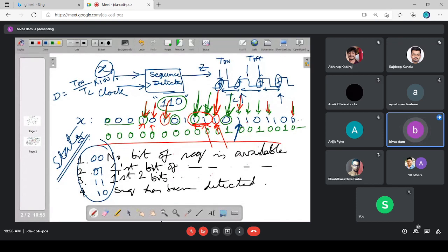Next, you have to assign state codes to those histories, and those state codes must be unique. Sir, can there be any other history apart from these four? In that case, your state assignment is not proper. You have to identify all possible histories. All means all. In this specific example, there are only 4 possibilities.